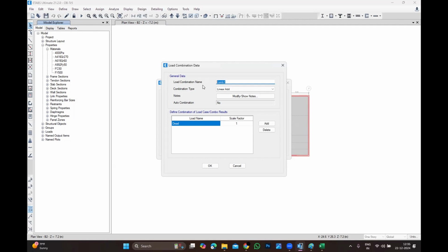On top of it, whatever you add, like bracing and such, is to control your drift. You could call it an outrigger, but it is not an outrigger. An outrigger is at a corresponding floor, usually a mechanical floor, where we introduce floor-to-floor deep beams and cross bracing. That is called an outrigger, purposefully to control your drift, not displacement. Don't confuse yourself.